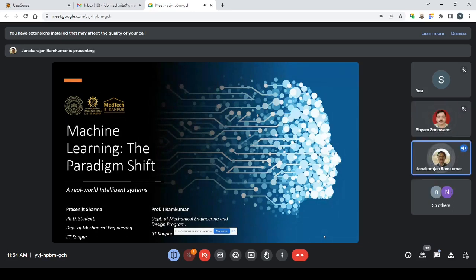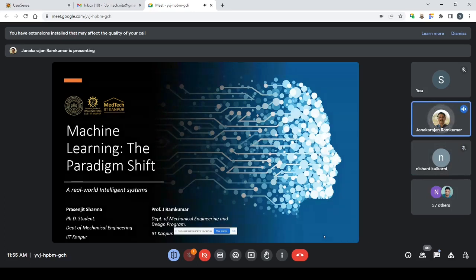Manufacturing is something very interesting. In manufacturing, if you look at it, there are only three important parameters. One is pressure, the second is time, and the third one is temperature. You can have all three, any two, or one. For example, heat treatment is time and temperature. Metal forming experiments are pressure and time. The difference between metal cutting and metal forming is basically the loads you apply and the time.